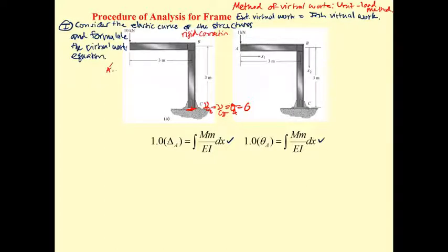By moving that, this frame is going to have some deflection, and the deflection is supposed to correspond to the support here. So this beam will deflect like this, and this portion should deflect like this, and the structure is going to have this kind of deformation. Since this is a rigid joint, the angle between the beam and the column was normal before, so later this one will also be at a normal angle.